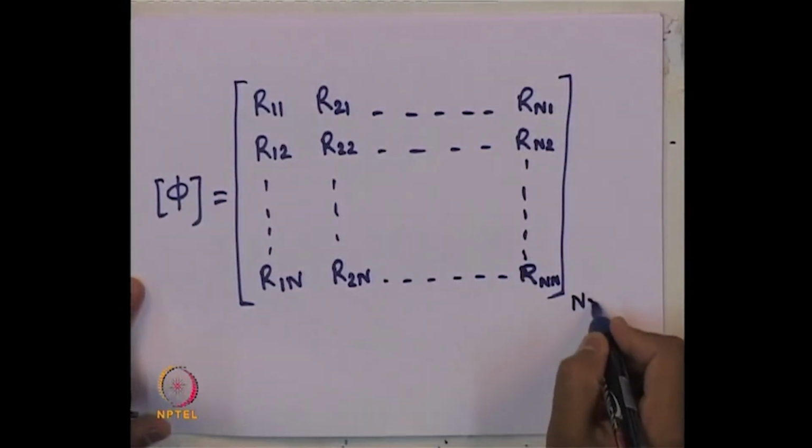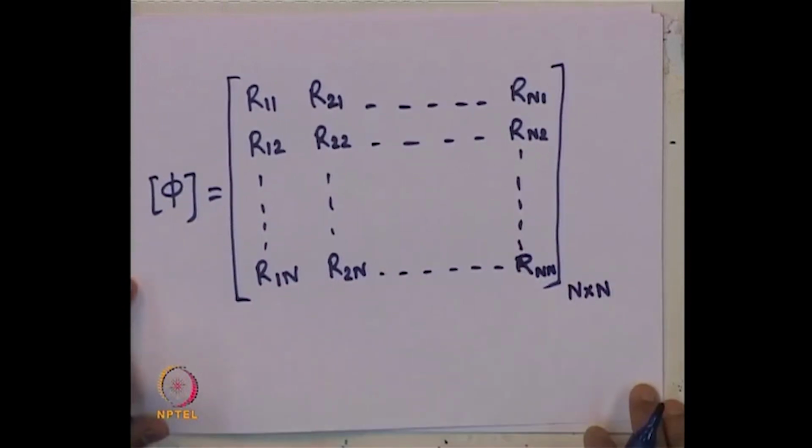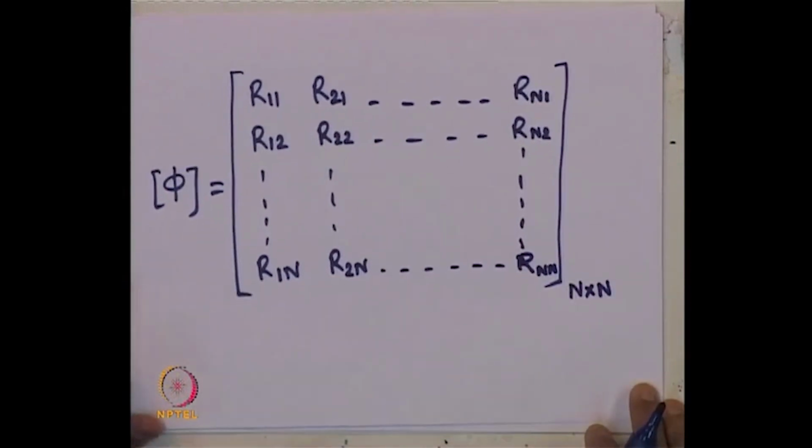So, this will be a transformation matrix of size n by n, as we have mentioned. Like this, using the transformation matrix, for any coordinate system and whatever equation of motion we got, if all the matrices are coupled or some of them are coupled and some uncoupled, we can transform them to our natural coordinate system, where all matrices are uncoupled or diagonal.